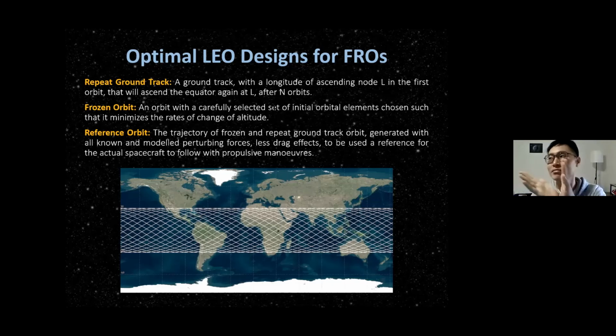then you can bring it up to different altitudes, just let it wait, and let the inclination slowly precess. For example, the Earth's bulginess makes a 2-body satellite orbit no longer constant. The orbit is wobbling around, the RAAN is precessing, and the inclination precesses a little bit. So you can exploit some of this if you have time, but it takes a really, really long time for your orbit parameters to precess a little bit.